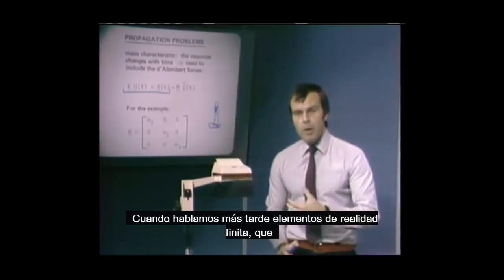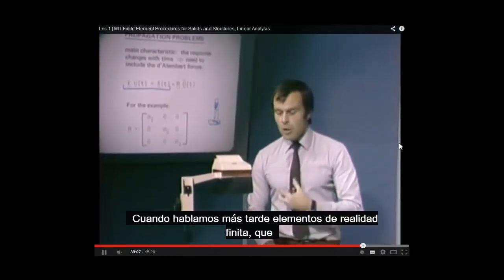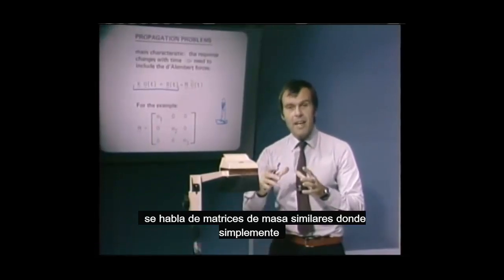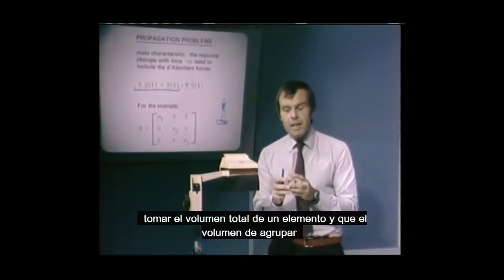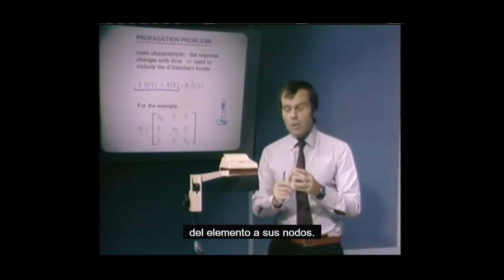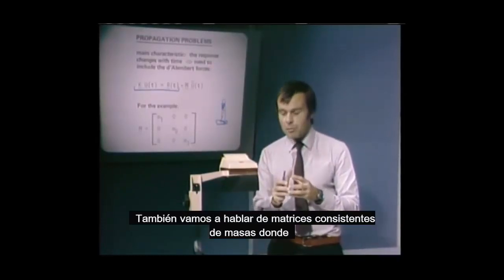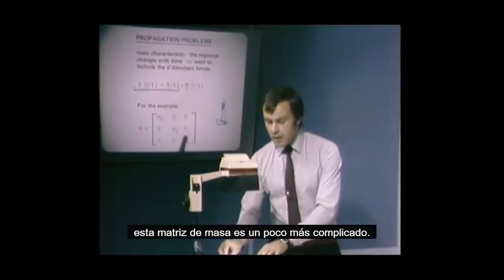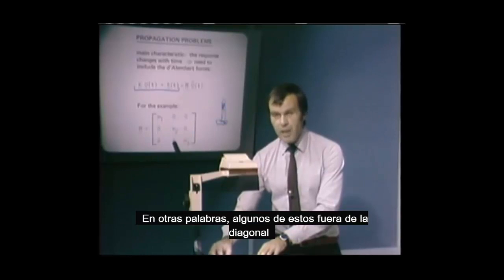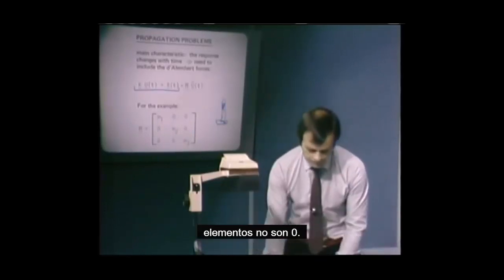When we talk later on about actual finite elements, we will be talking about similar mass matrices where we will simply take the total volume of an element and lump that volume of the element to its nodes. We will also talk about consistent mass matrices where this mass matrix is a little bit more complicated. In other words, some of these off-diagonal elements are not zero.